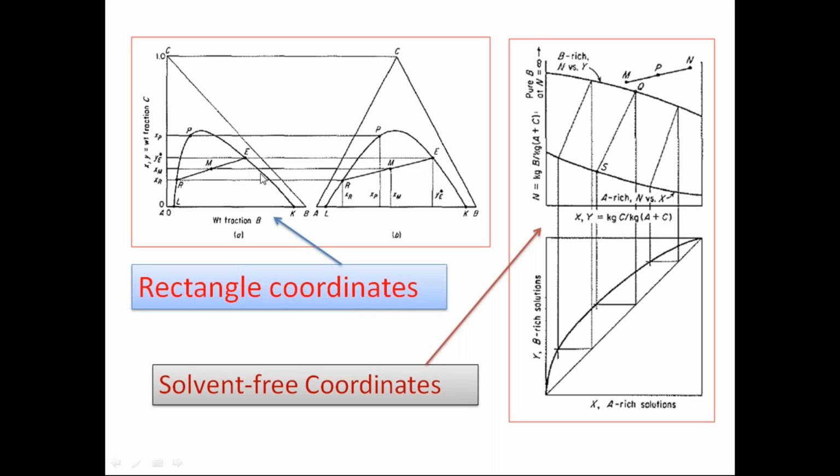Where exactly it is turning from homogeneous to heterogeneous: homogeneous will have no turbidity in the solution, and when the heterogeneous phase starts forming, then you can see an oily nature, that is the turbidity, in the solution. Therefore that is the starting point of the heterogeneous phase. Like that you can draw these lines. So this line is again called the binodal curve.